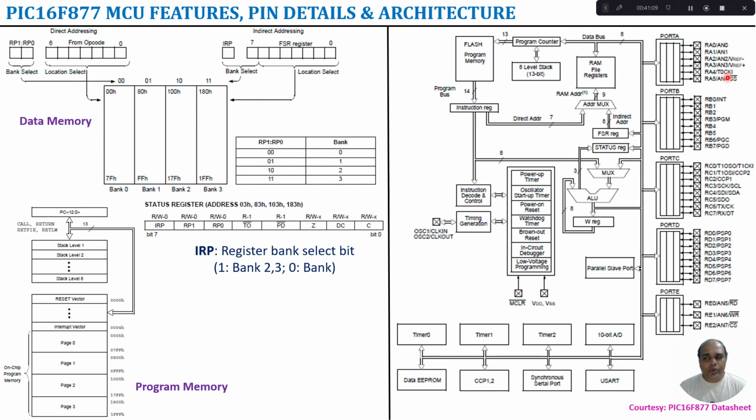I2C is a 2-wire protocol. It requires a clock signal, which is SCL, serial clock. SDA is serial data. So SCL and SDA are related to the I2C protocol. Again, it can be configured in a master-slave configuration. We also have the USART protocol, serial data transfer using USART. There I can use transmitter and receiver pins in asynchronous mode. In synchronous mode, we use clock and data.